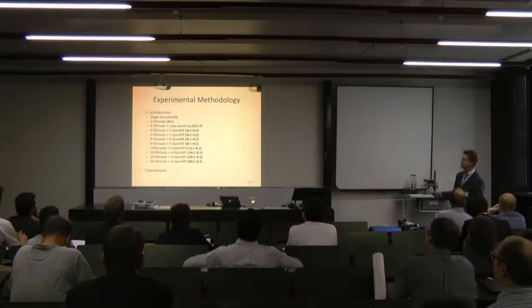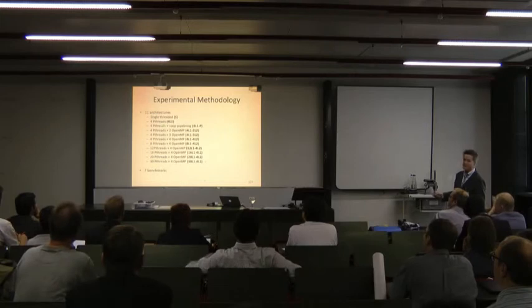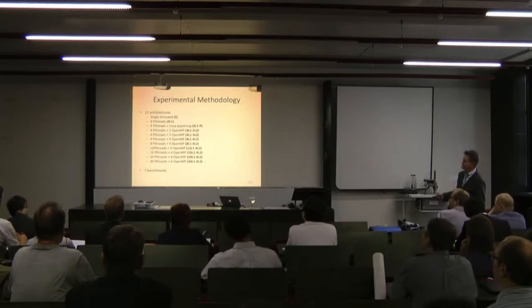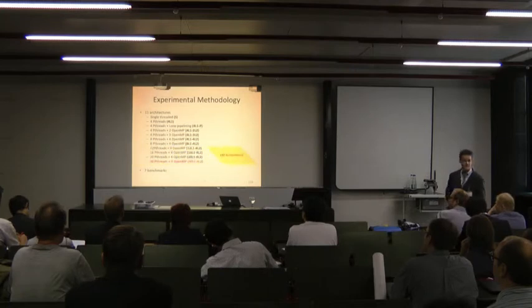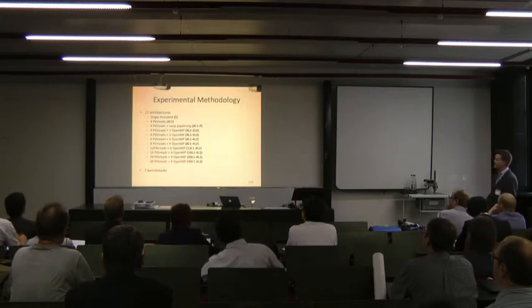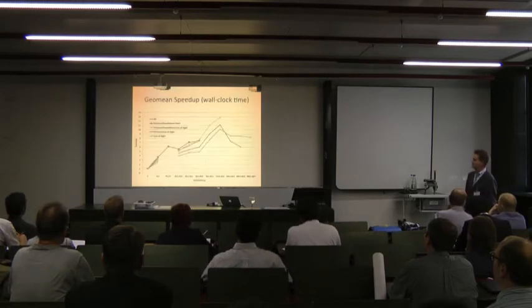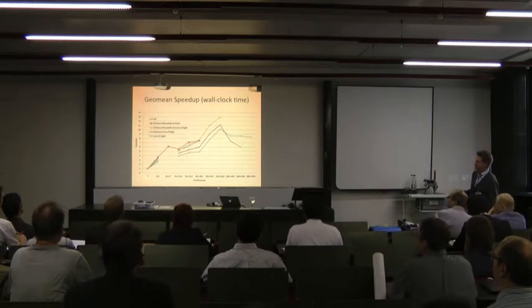different architectures for circuits: single-threaded, 4 level 1 threads, 4 level 1 threads with loop pipelining inside, as well as different numbers of level 1 and level 2 threads, where in some cases we actually had up to 120 accelerators, where 30 were level 1 threads, and inside each of those had 4 OpenMP accelerators. We used 7 benchmarks for this, targeting the Altera Stratix 4. To show you a few result highlights, here you see the architectures going from sequential up to that case where we had 120 accelerators.